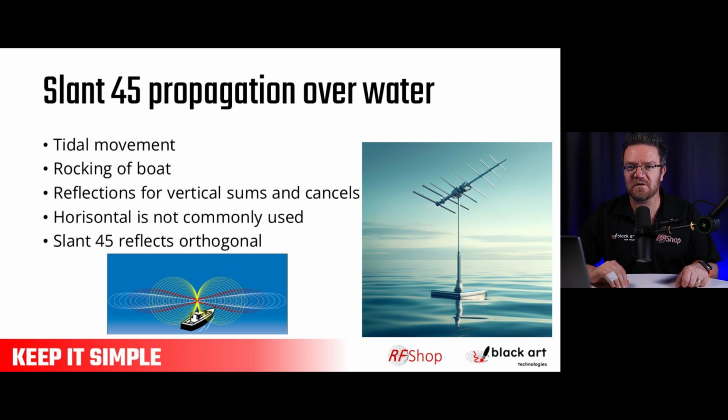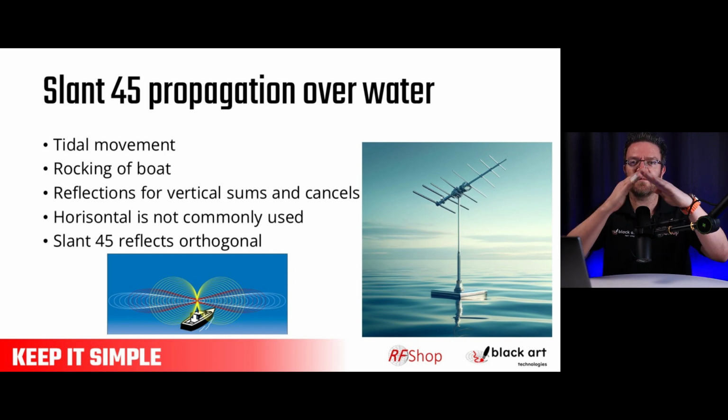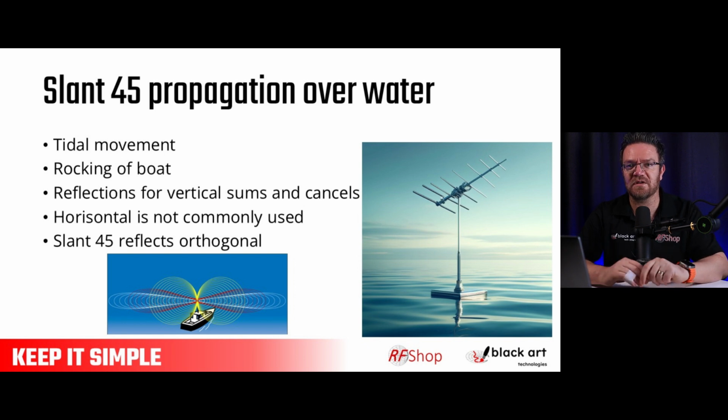Now, if you have cross polarization discrimination, in other words, you are not so effective in your orthogonal direction, which is what the typical dipole or LPDA would be, that helps a lot, because suddenly you can reduce your sensitivity to reflection. It's a simple trick. It's a very powerful trick to use, but you need to know the fundamentals of your antenna design.